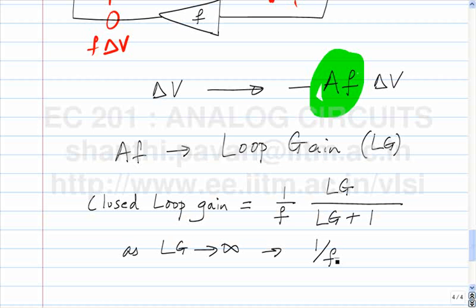Why? As we saw before, if you take two resistors in series, the feedback ratio F is a dimensionless quantity in this case. So it can be made to be a ratio of like quantities. So it's very easy and straightforward to get an attenuator whose properties are independent of temperature.